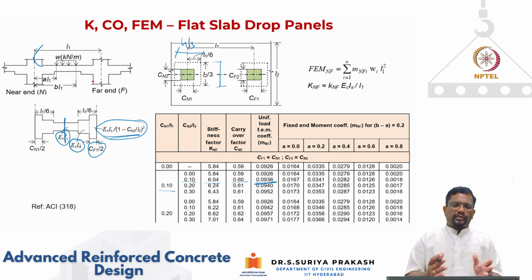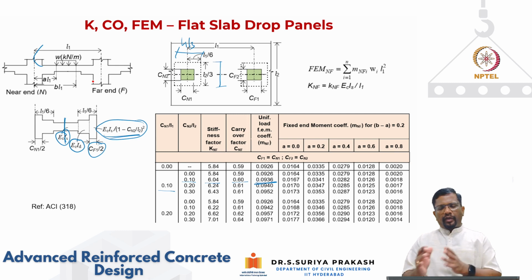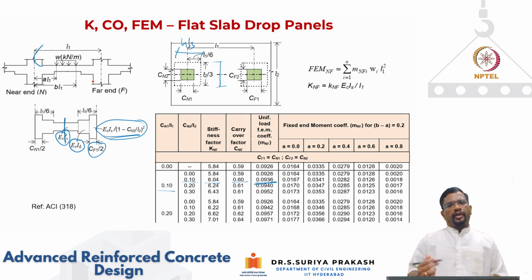Okay. Again, for this loading and this configuration of flat slab, depending upon what the column dimensions are and what the span is, you can use these tables to find this K factor, carryover factor, and fixed end moment coefficient, right?